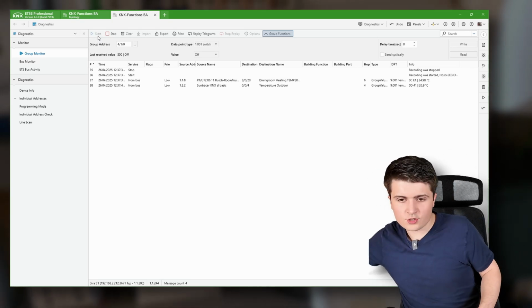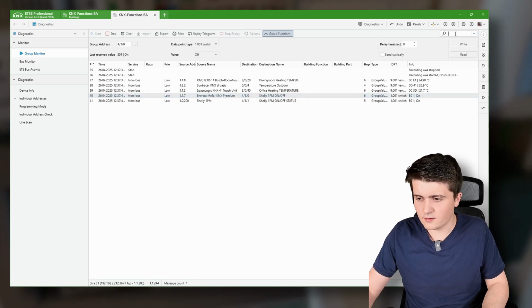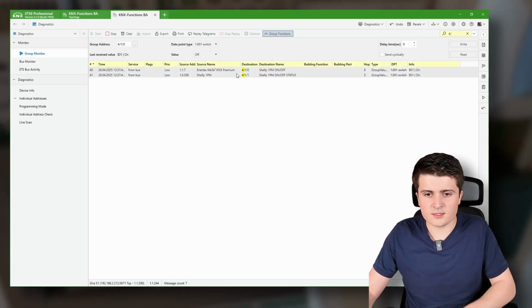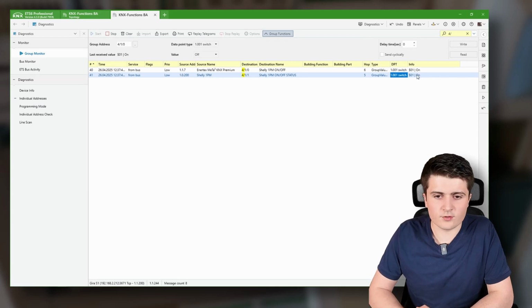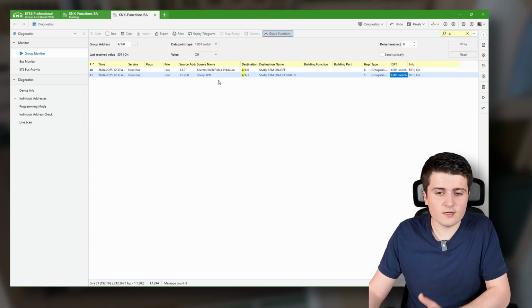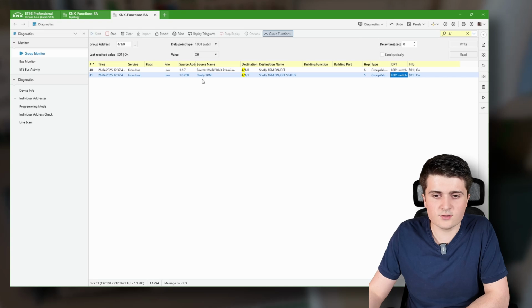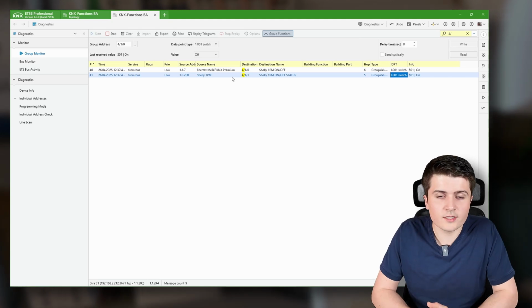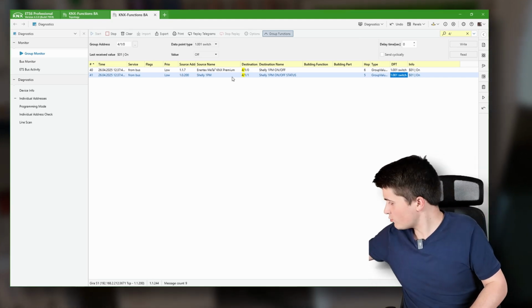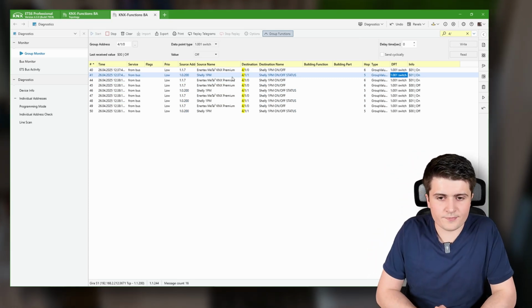And if I now turn the Shelly on with my push button sensor, I will quickly filter for the group addresses here. So here we can see, here was my push button sensor, I sent the telegram on, and then the Shelly was responding with the value on. And so now the EDS knows everything, and because we also renamed the device and set it to the correct physical address the Shelly device is using, we can also see it being shown in the diagnostics. And with that I can now control the Shelly device with my KNX push button sensor.